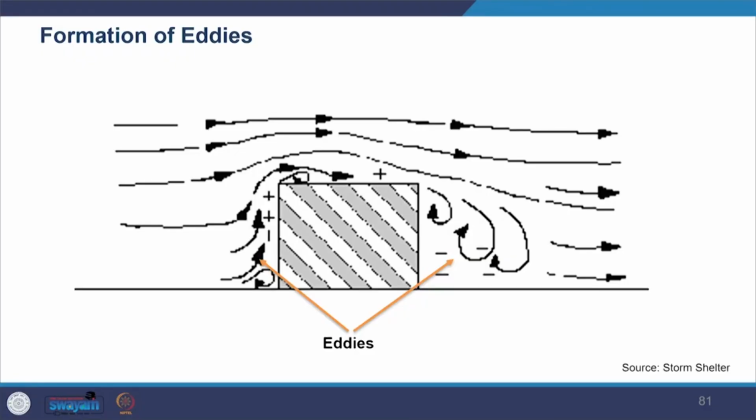Also, whenever tall buildings are adjoining the facility, wind can sometimes give rise to high ground level concentration. Such a situation arises due to the formation of eddies around the building that make the plume touch the ground much closer. In the absence of the building, these plumes would not have hit the ground. It is usually understood that building downwash problems occur if the stack height is less than 2.5 times the height of the building above which it projects.